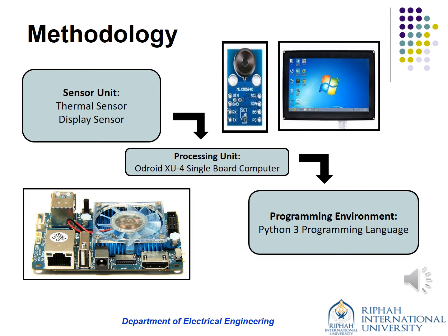This board contains a real-time current sensor that measures the power consumption in 4 separate domains, like A7, A15, GPU, and DRAM. The processing unit contains all components like the camera unit, with an I2C interface, and the display unit with the HDMI interface, as a system for data acquisition and showing the result.